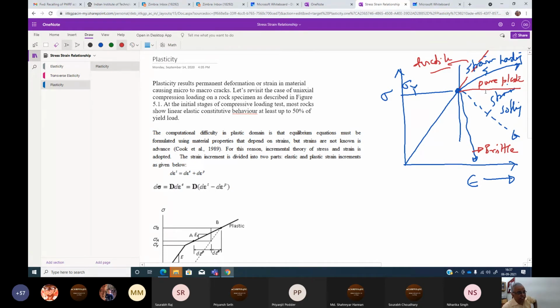Our rock is somewhere in between. Most of the rocks are strain softening; they gradually shed load. But there are some granites that are like brittle, and some igneous formations are highly brittle. Marble is not so, but some marbles are also very brittle. Once it's cracked, it is gone, we normally say, and its valuation just goes down like anything. Otherwise, marble is very expensive.